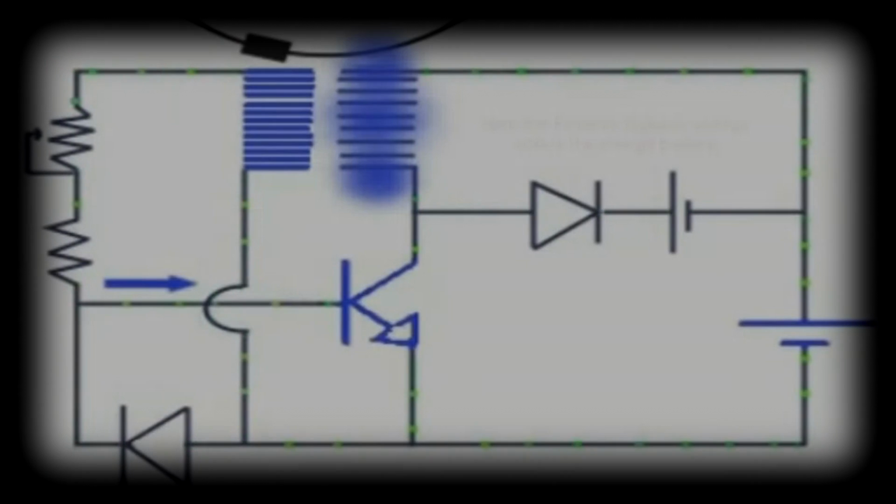And then the magnet passes fully over the trigger winding, and now there's enough current to activate that transistor for that duty cycle based on the amount of current that the rotor magnet induced onto this trigger winding. So now the trigger winding has fully triggered and closed the gate on the transistor. You could see that because the drive coil is now charging.